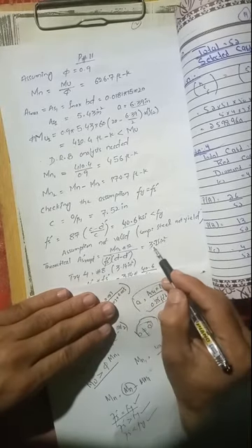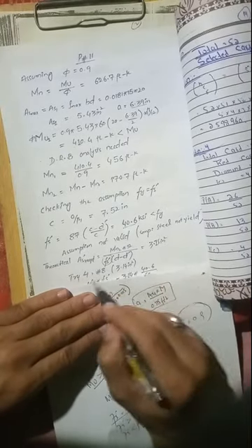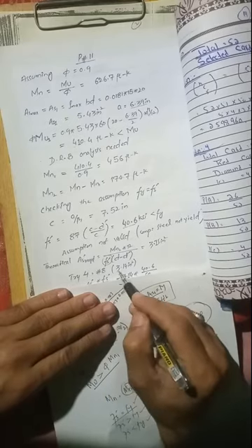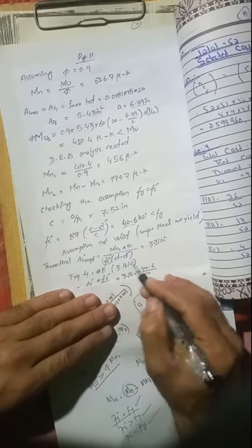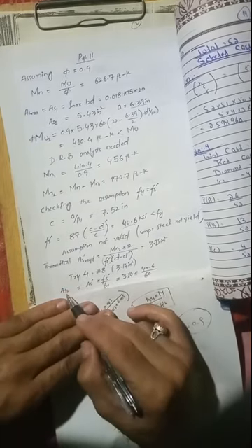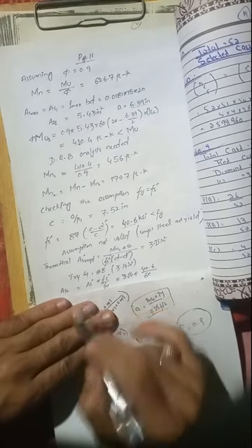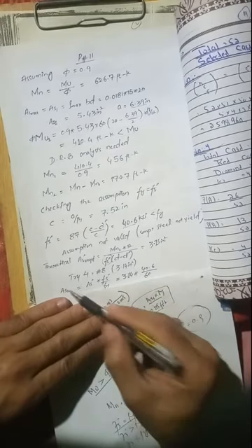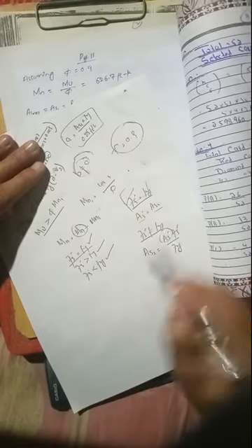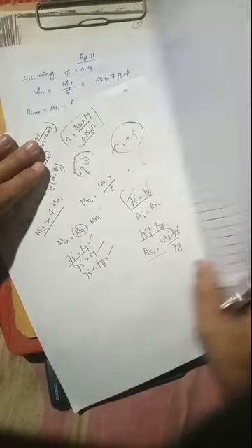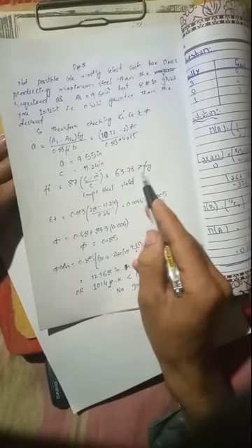So here we have 3.15 square inch. For this reinforcement we use 4 number 8 bars, 3.14, a little bit lower value. Okay, this is also a very important point, right? So again we are using the relationship for As2, remember. This is why we are not using As prime equals As2, because fs prime is not equal to fy. In that example we didn't use this check, we didn't use this relationship, because there fs prime is greater than fy.